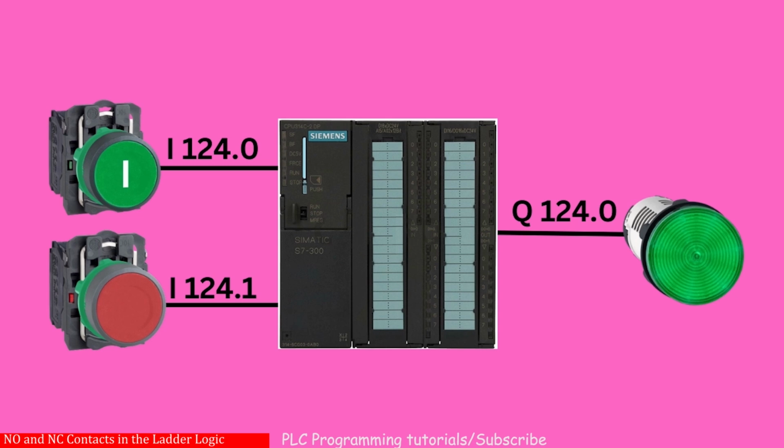For today's tutorial, we have connected two push buttons at the two inputs I124.0 and I124.1 of the PLC, and one output LED is connected at the Q124.0 output of the PLC. So in this example, we are going to see how we can use the normal open and normal close contacts to make a simple hold on logic.